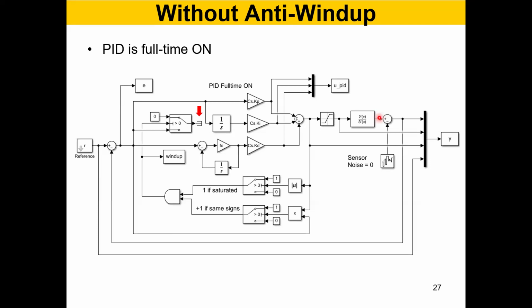So now you have the option. You don't have to feed back the noisy response, but you can get the Kalman filter output, the true response estimate, and feed back that one. Because there's no point in feeding back the sensor reading knowing that it has noise. So why should I feed back a noisy response? You got that point? We need to feed back the response without sensor noise. We don't want to feed back sensor noise. That's why the Kalman filter estimates the true response over here before you add the sensor noise.